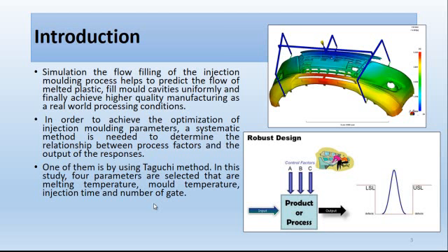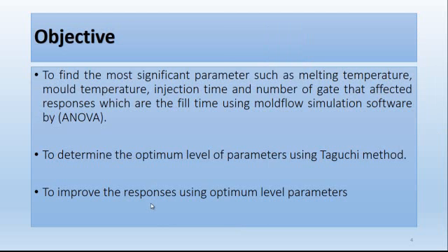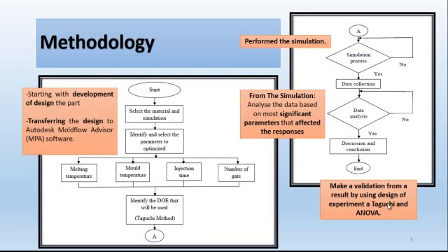using some sophisticated method. The objective of this project is first to find the most significant parameters such as melting temperature, mold temperature, injection time, and the number of gates that affected the response, which is fill time using Moldflow simulation software. Second, to determine the optimum level of parameter using Taguchi method, and last is to improve the response using optimal level parameter. This flowchart shows the methodology of this project.